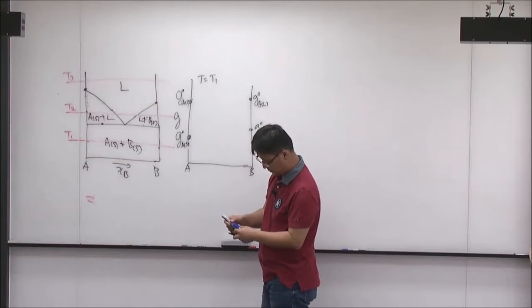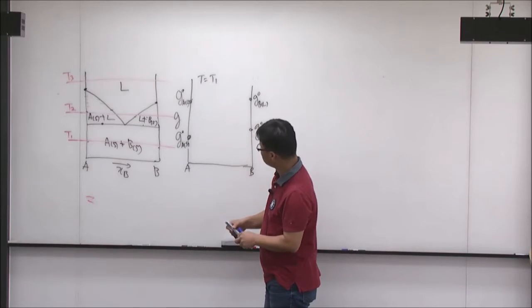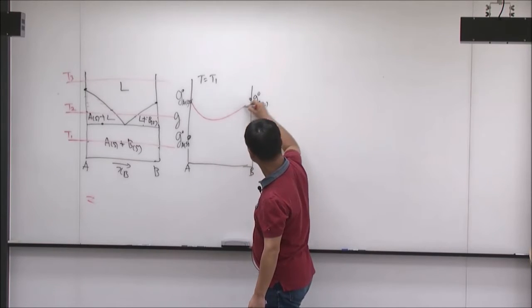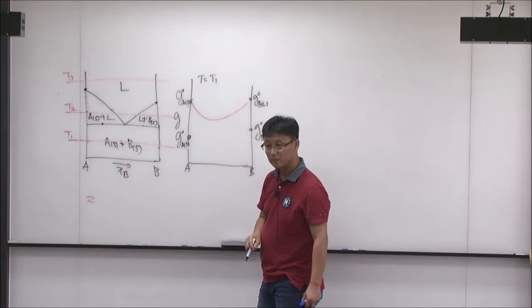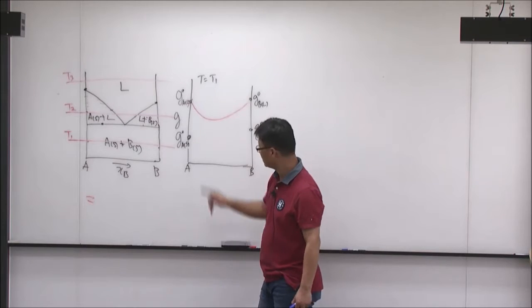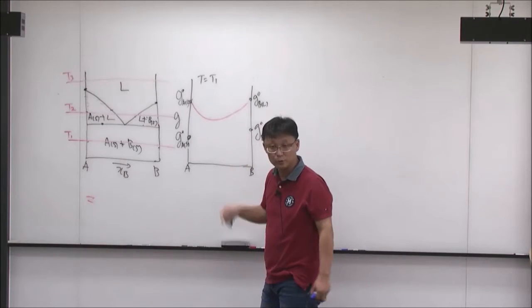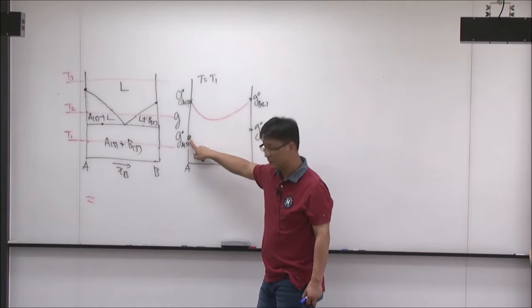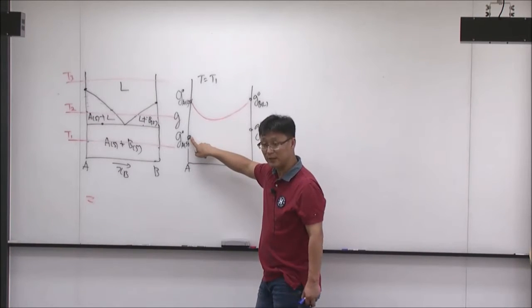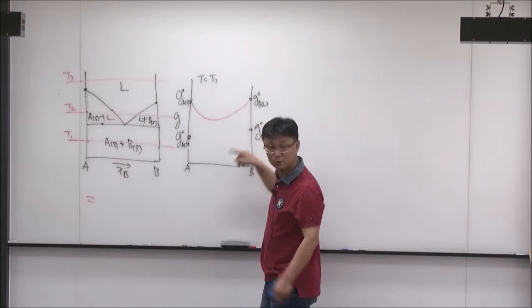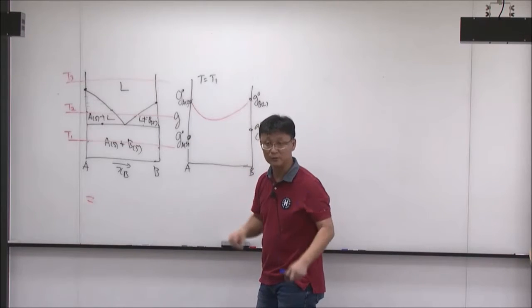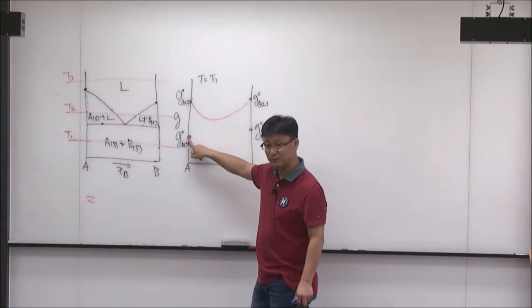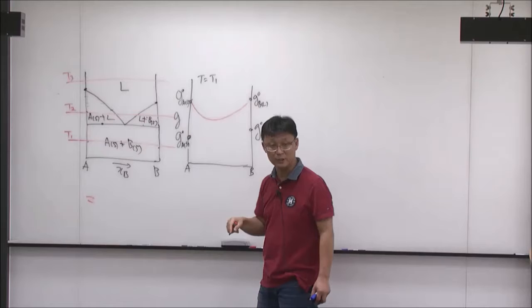And then, now, Gibbs energy of liquid phase. Okay? Gibbs energy of solid phase, A and B, because there's no solution. Okay? So this is just Gibbs energy of A solid. I say solid, but for example, this may be FCC, this may be BCC, two different crystallographic structures. So there's no solubility in each other. Then you have just a single Gibbs energy point here, a single Gibbs energy point there.